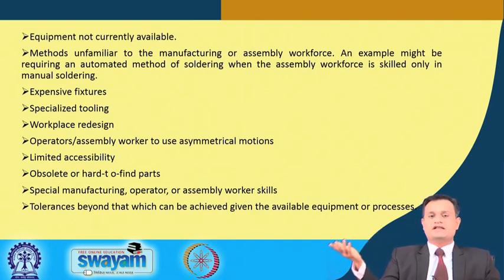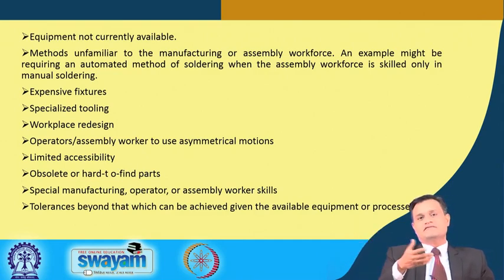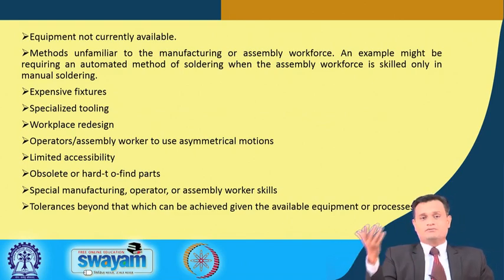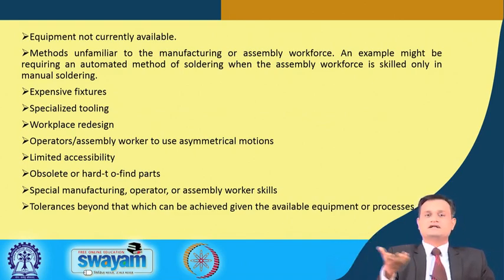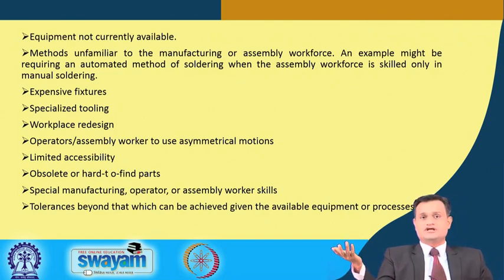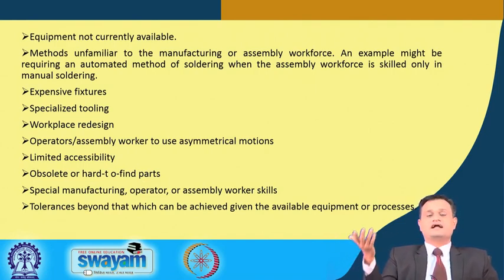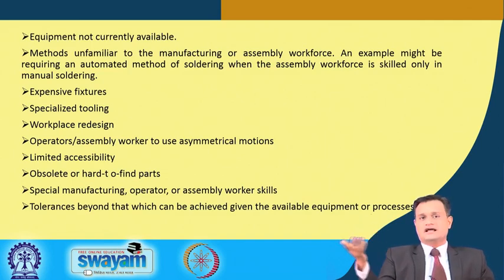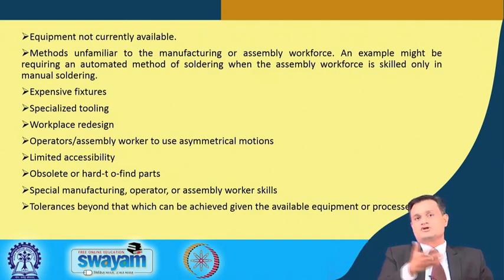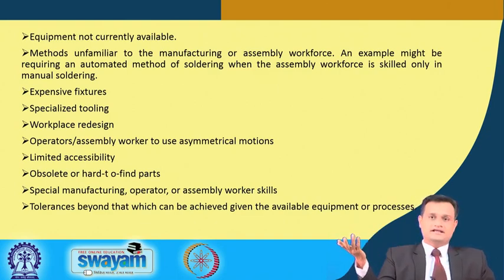Methods unfamiliar to the manufacturing or assembly workforce. The way you have decided the specification and design requirements, the kind of processes or methods it demands are very much unfamiliar, and you will end up with either too much training or a very poor performance of the people. Expensive fixtures. You already have fixtures, but now your design is demanding altogether different kinds of expensive fixtures. Again, this has some impact on the performance of your downstream stakeholders and calls for DFX.